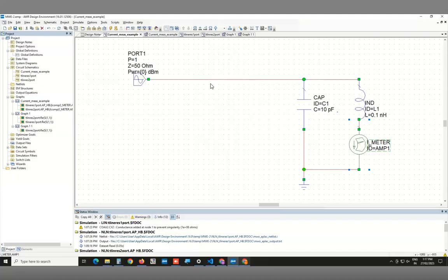Now that coupling capacitor has the effect of changing the frequency of the resonator as well. If it's small, then it will be a small effect, but it has a finite effect. And we had talked about the fact that you can think that this series capacitance through the source is sort of connected to ground, so it is in parallel. But the real way is, I forget now if it was in one of the problems, where we had asked you to compute the effect of a series RC and model it as a parallel RC at one particular frequency.